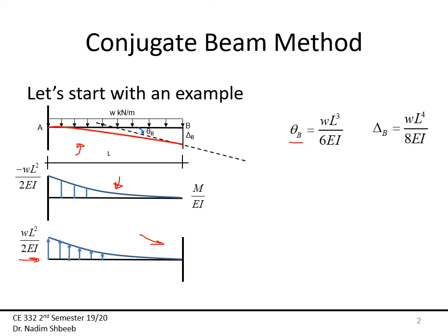Okay. Now, then we drop the moment diagram, and we assume that this is now the load on this beam that we just made up. Okay, so we made up this beam. This beam does not exist. All right. Now you've noticed that the arrows are going away from the beam, and since I'm drawing on the tension side, then usually the direction of the load in my way is always away from the beam. Okay. So now for this beam, can I find the reaction?